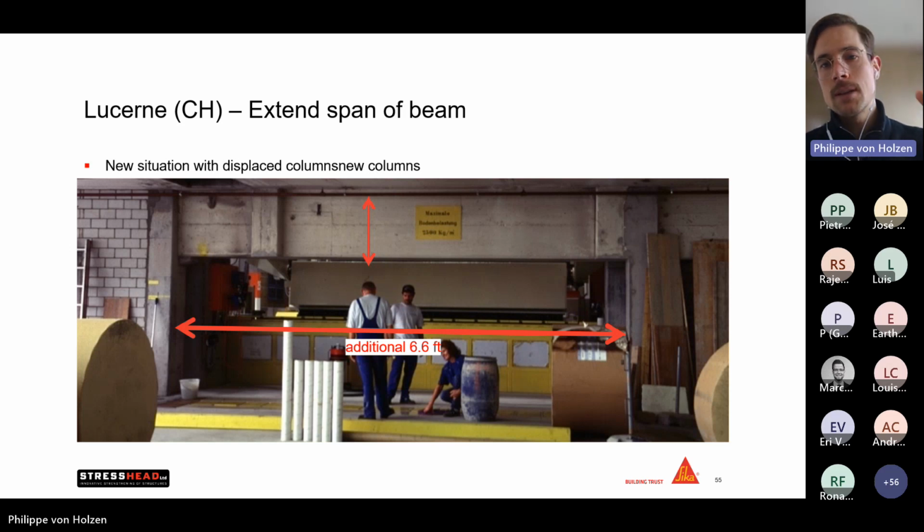The problem would have been that there would have been too much overhead height lost due to the installation. Now, as the system is so thin, only 2.5 millimeters, let's say with applying it with the epoxy we're talking about around 3 millimeters, you will have no loss of this overhead height due to the installation of the system.